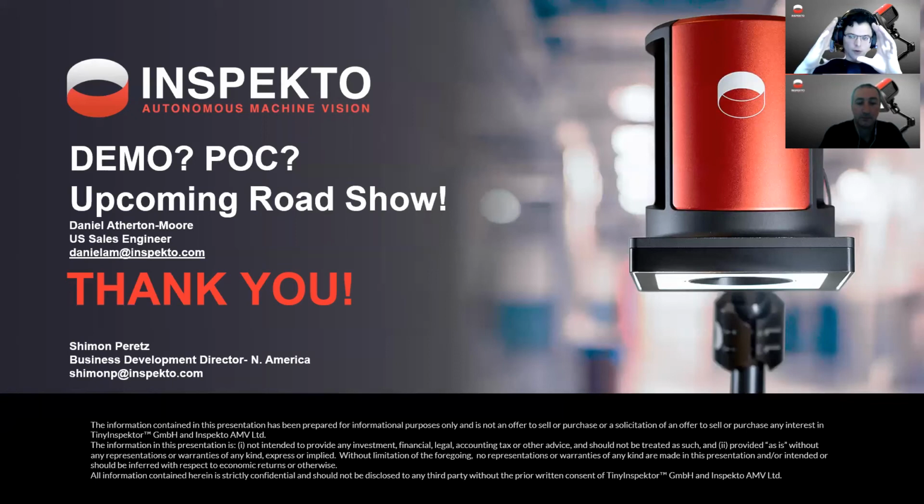So the closer you are, the more information you're going to get out of the surface, the further away, the less information. So you're going to be mounted further away for looking at large parts, and you will get a little less information about the surface quality. If you need a ton of information over a very large part, you can mount multiple cameras. And I'll say, okay, this camera is monitoring quadrant 1, this has got quadrant 2, and they'll all work together to inspect the part for you.